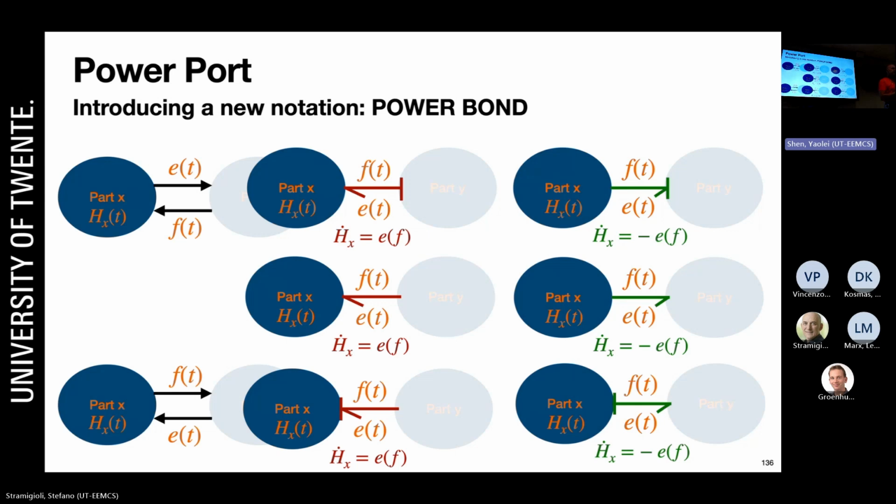And I think that was the notation that was using. So if you have a half arrow, so if I write something like this, I'm stopping in that, but it is important actually. So if I write a bond like that, and I want to indicate the two variables like force and velocity, for example, current and voltage, okay, then I would write it like this. I say, for example, force and velocity, which means this is the effort, this is the flow. Okay. But you could dualize, you can always dualize things, we'll see that.